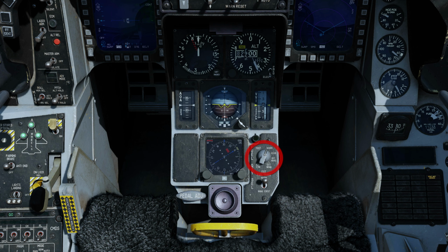In the normal position, the aft left needle displays the fuel quantity in the aft left reservoir and A1 fuselage tanks, while the forward right needle displays the fuel quantity in the forward right reservoir and F1 and F2 fuselage tanks. The totalizer displays the total fuel amount available. The automatic forward fuel transfer system, trapped fuel warning and bingo fuel computation are only enabled in the normal position.